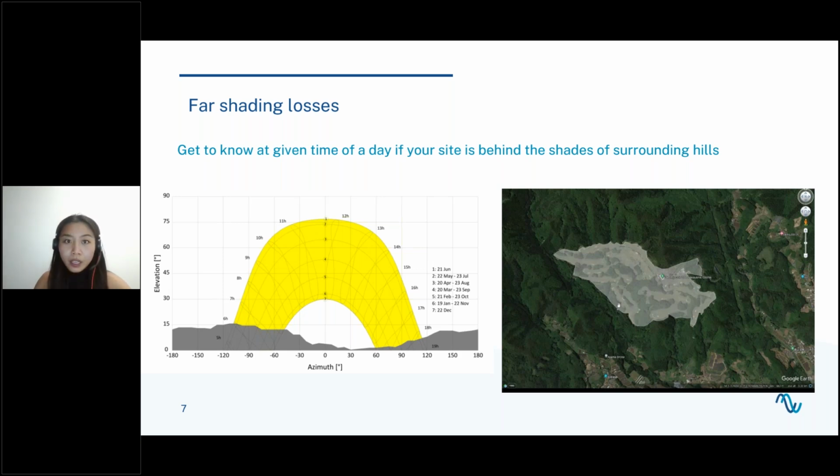Okay. And another case, can PV design generate P90 and P95 scenarios? The answer is yes. I have actually mentioned this earlier. We do give the users a probability study on the energy results from P50 to P99, and it all depends on this interannual variability figure that the user has defined.